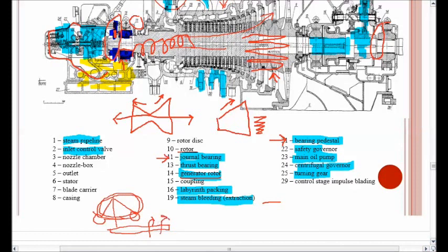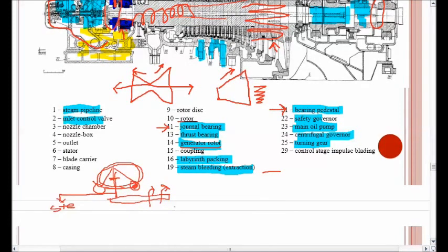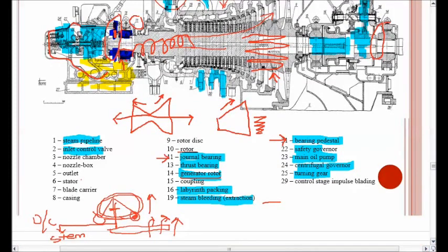As the speed of the rotor increases, because of these fly balls, a lever that's connected between the main shaft and the steam inlet is affected. When the turbine speed increases, the flyballs go up because of the centrifugal force, because of which a steam valve is opened or closed accordingly so as to control the steam.